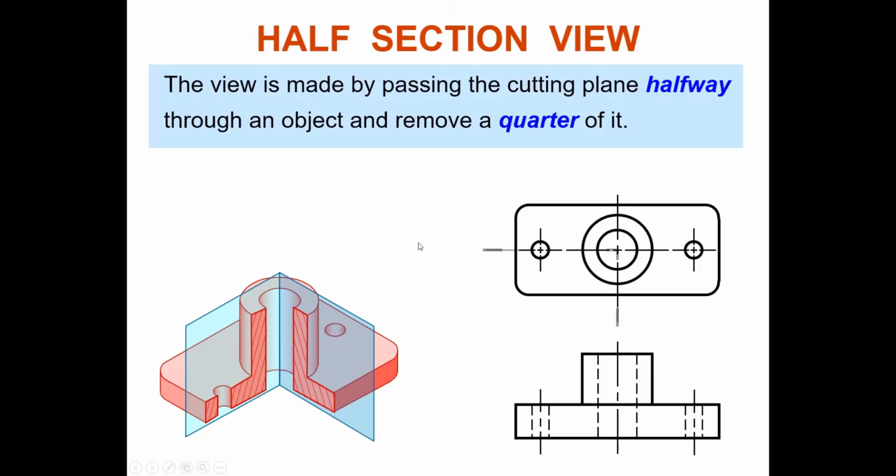Look at your top view. We have the cut, and this is your viewing direction. If we look at your plan view, we have thicker lines here, kind of like an L. The corner is also thicker, and at the end here thicker. It's kind of like a center line. Can you see your center line to your section line is L shape? The end is thicker, the L-shaped corner is thicker, and at the bottom end here thicker.